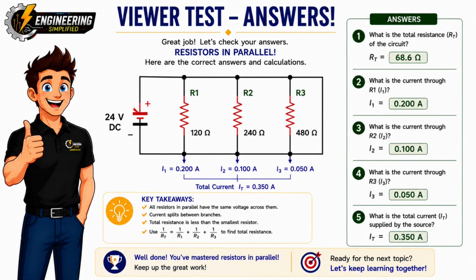The first question was to calculate the total resistance of the parallel network. Using the reciprocal formula, the answer is 68.6 ohms. Next, we found the current flowing through each branch. Since every resistor has the full 24 volts across it, we simply applied Ohm's law to each resistor individually. For R1, the current is 0.200 amps.